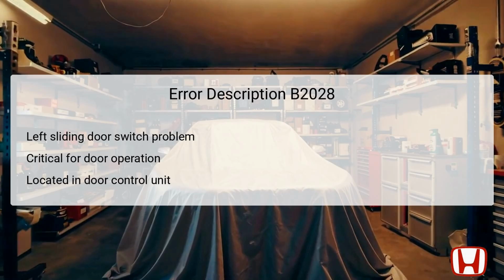The remote control switch is integrated within the left sliding door's electrical system, and it interacts with the power sliding door control unit to perform its functions. If this switch does not send the correct signals, it can hinder the door's operation, causing it not to open or close as expected. The intricacy of this system means that comprehending the role of each component is vital for effective troubleshooting. Its failure can often lead to inconvenience, making it crucial to maintain its functionality. Understanding its location and role will aid in fast diagnosis and service.